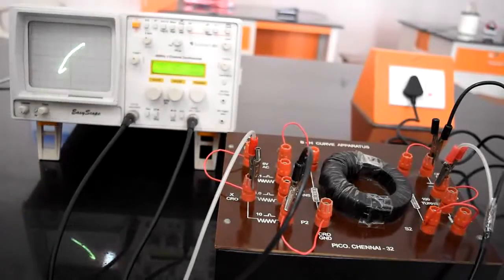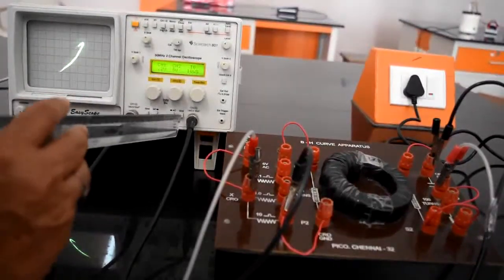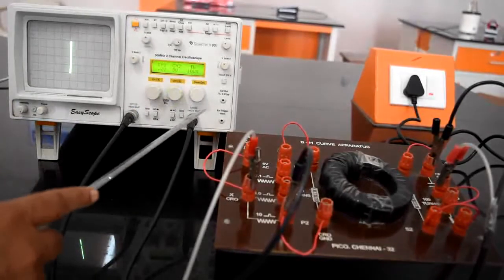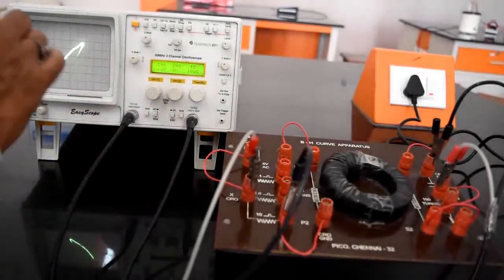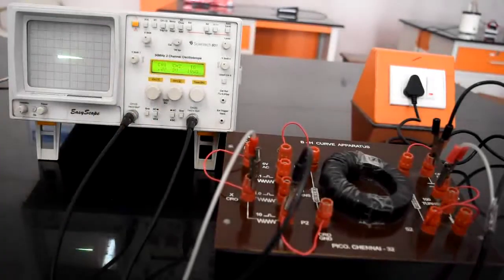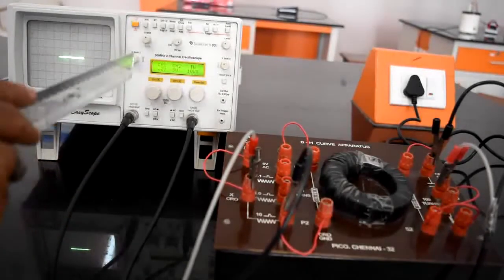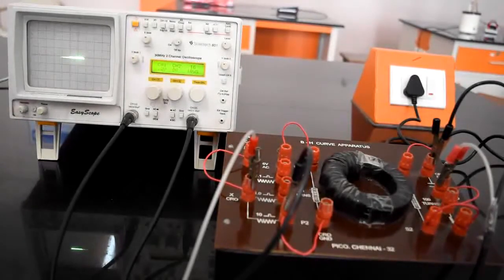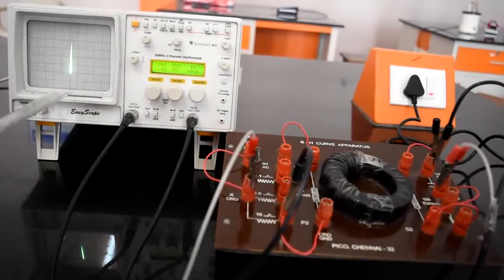How to get Lx? To get Lx, you see that the Y input has two knobs, and one knob is ground. You make this a ground by pressing like this. What you are seeing is that the X input is made ground, and we have a vertical line length. If you release it, you get the same curve. If you make Y CRO ground, this is the Y connection, channel 1, connected to ground by pressing the ground, so we have a horizontal line. This length is measured, and that is called Lx. And if you want Ly, you take Lx to ground. Lx is grounded, so we have Ly. This length is called Ly, 4 centimeter.